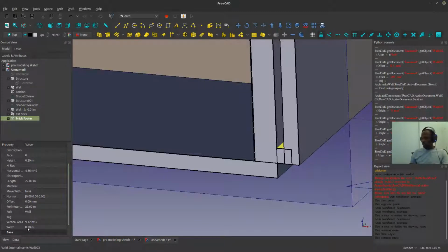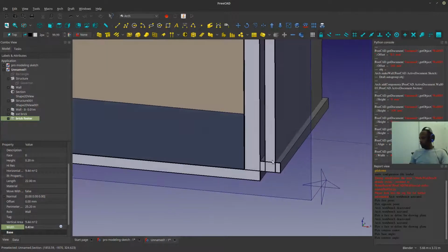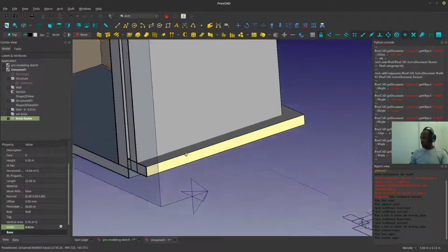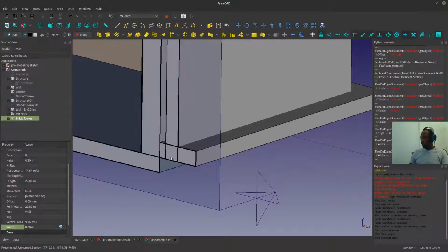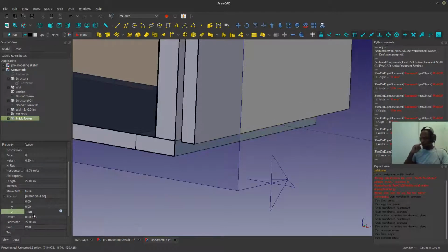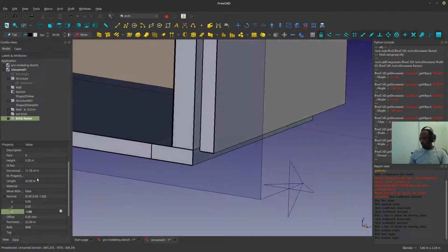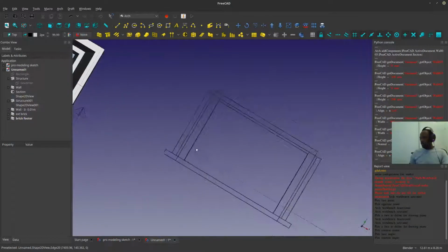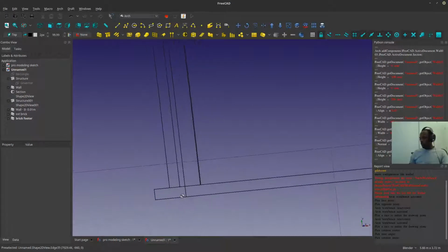And now I'm gonna change its thickness. The width will be, let's say 4, yeah, 4 is good. No, maybe 6. Let's go with 6. Okay. But you see, it's still on top of the ground level. I want it to be below. So what you would do is change the normal where you'd say -1. And so with -1, it went back to its original position. So what you do in that instance is change the alignment where you tell it to be right instead, like that.